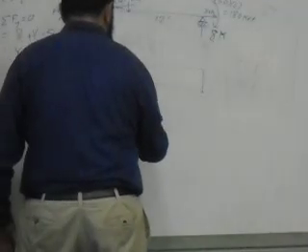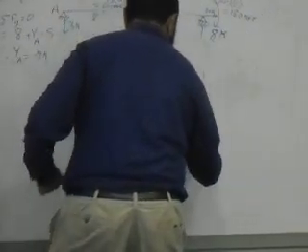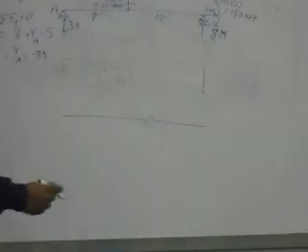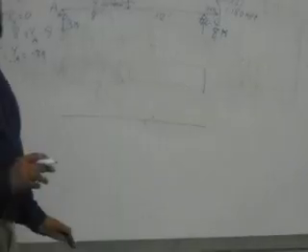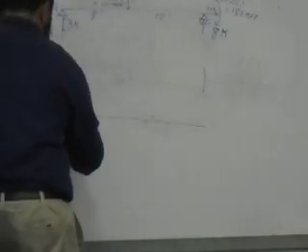Okay, let's talk about the bending moment diagram. Look with me now. Again, at this point, I know that this point is 0 for sure. At the edge, there is nothing beside me, and there is no concentrated point, so this point is 0. However, what's happening here, I'm having a concentrated moment. It's another story.